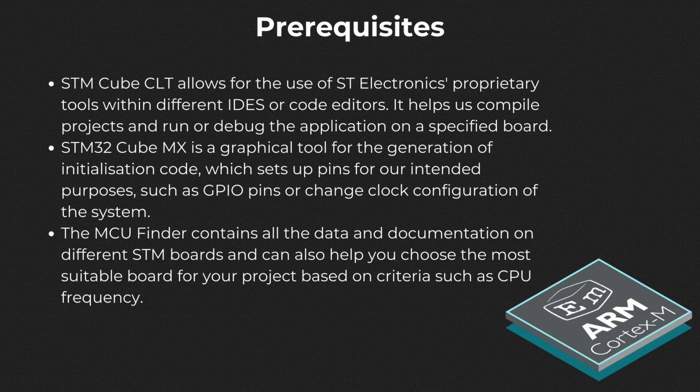The STM32 extension allows for the use of ST Electronics proprietary tools within different IDEs or code editors. It helps us compile projects and run or debug the application on a specified board. STM32CubeMX is a graphical tool for generating initialization code, which means it can set up pins for our intended purpose, such as GPIO pins, or change the clock configuration of the system.